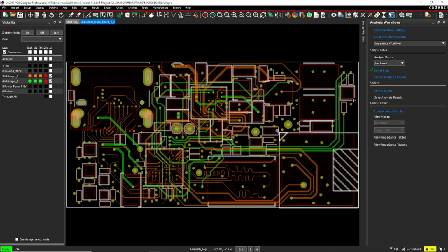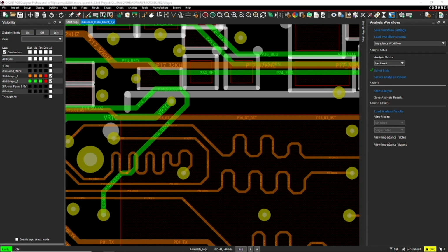But what if you did have to do these calculations on your own? Well, you would need to do the following. First, you'd need to calculate the required delay or timing for an acceptable signal timing mismatch for the microcontroller. Then use a combination of the IBIS model for the chip. Then understand the type of dielectric material to determine the signal propagation velocity and delay. Then, subsequently, with the signal timing for the traces, you can decide how much to delay the signal by. Like, say, adding a trombone or accordion style delay tuning method for the trace.